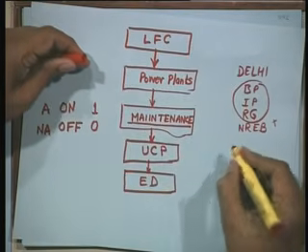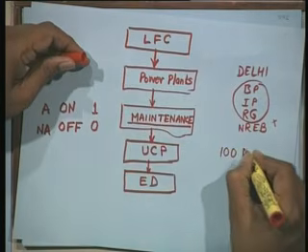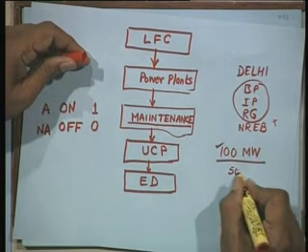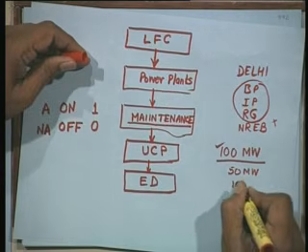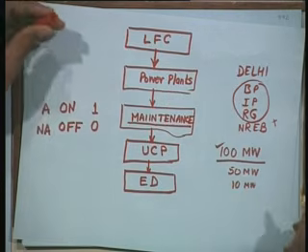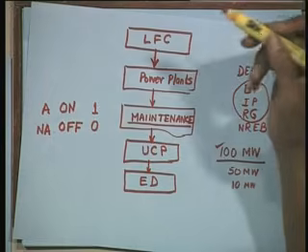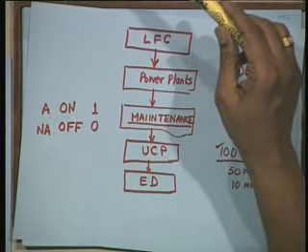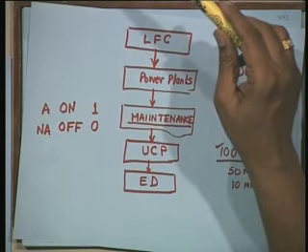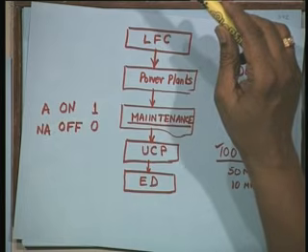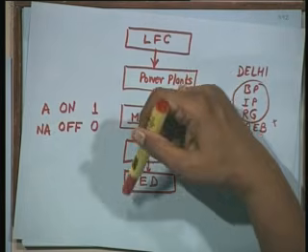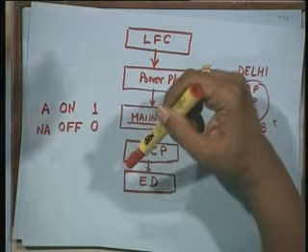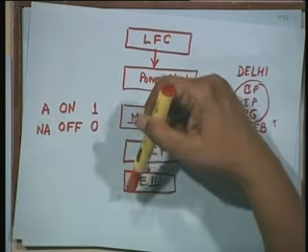Suppose it is a 100 megawatt unit, should you load it fully to 100 megawatt or 50 megawatt or 10 megawatt or any other number, depending on the need, depending on some objective function: economy, reliability, security, emission, voltage control, etc. This ED will give you, for the units which are available and willing to take load, how much load they will carry. That solution will come from ED.